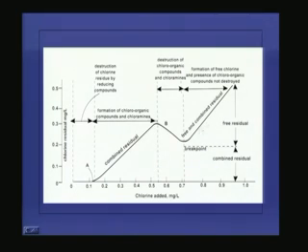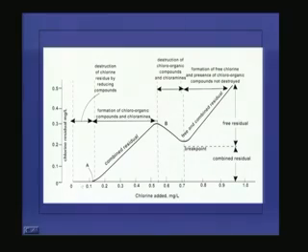So, this is known as the breakpoint curve. It is very important. Initially, up to here, the residual chlorine is almost nil, because the chlorine is used for the destruction of other compounds. We have seen that if organic matter is present, it will be used for the destruction of organic matter. Then if microorganisms are there, they also get destroyed. So some amount of chlorine will be used for the destruction of the organic compounds present in the system, so there will not be any residual chlorine at all.